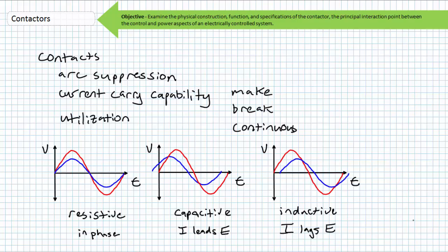The mechanical linkages, springs, and the contacts internal to the contactor must be periodically inspected for proper operation and signs of mechanical wear. Misalignment of the contact carrier or any obstructions will prevent movement of the contacts. Closure should ideally be as rapid as possible. However, contact bounce at closing can form an arc.